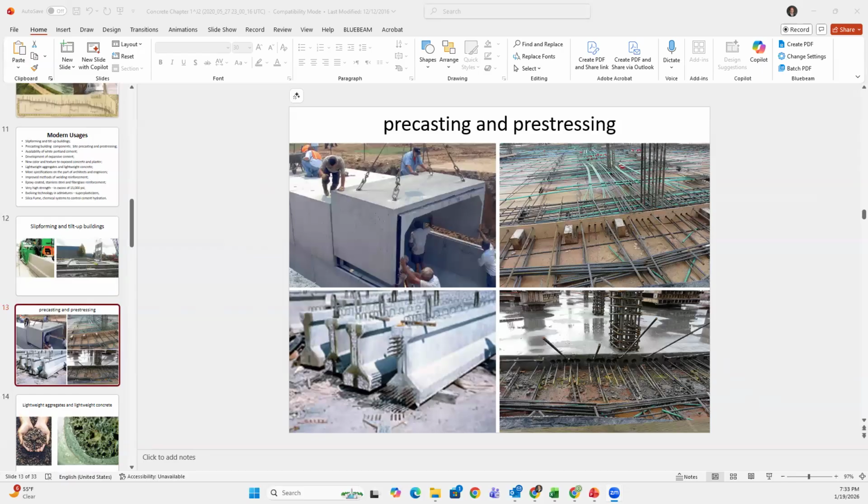They're going to become stiff. And so that's what you do with a slab: after it cures for maybe 10 days, whatever they specify, then you will put tension on it. And they go up to anywhere from 30 to 90,000 pounds of force, of tension on those cables. So they're in tension. That's why it's called post-tension.